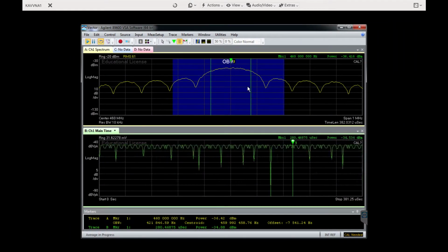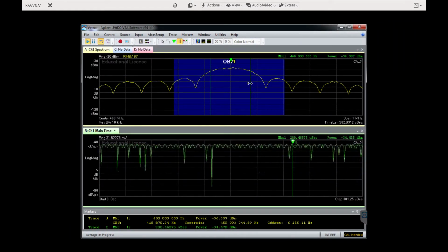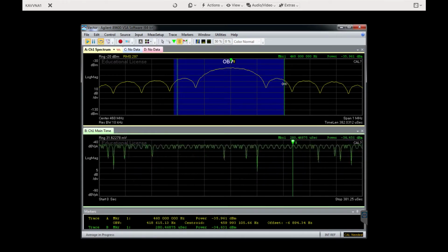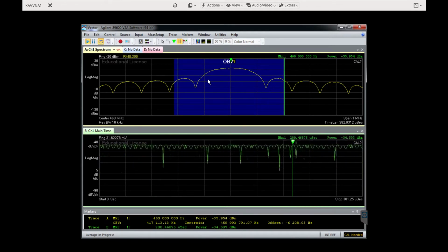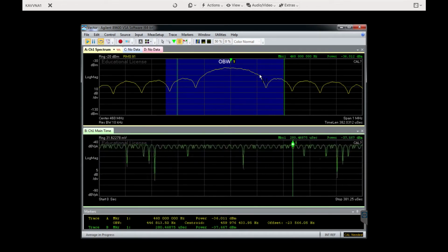Here at the receiver side, we notice a severe effect of such truncation, where the occupied bandwidth is much more and the side lobes are much larger. Actually, with such truncation, the root raised cosine filter is not a root raised cosine filter anymore.